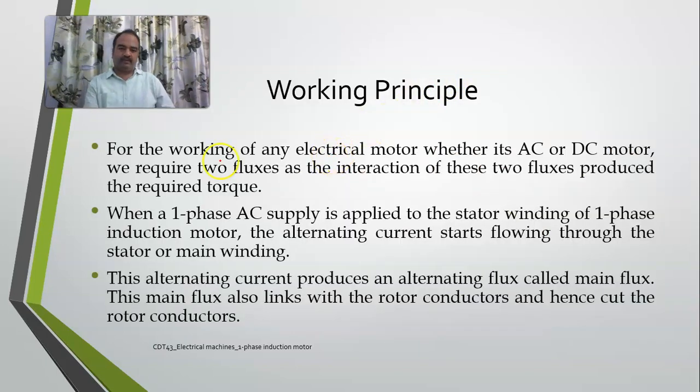Now, as already said, we have seen in the three phase induction motor that for working of an electrical motor, we do require two fluxes, right? Whether it is AC or DC, we require two fluxes. Interaction of these two fluxes only will give you the required torque. So when you provide single phase AC supply to the stator winding of a single phase induction motor, you are getting only one flux, right?